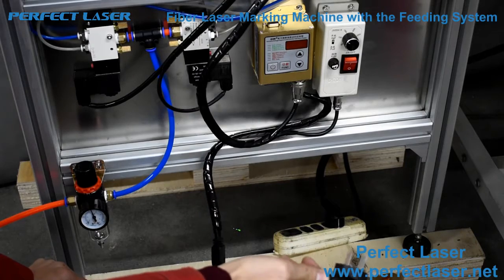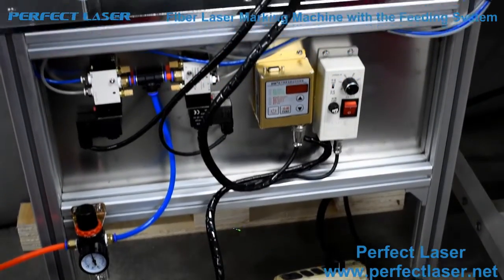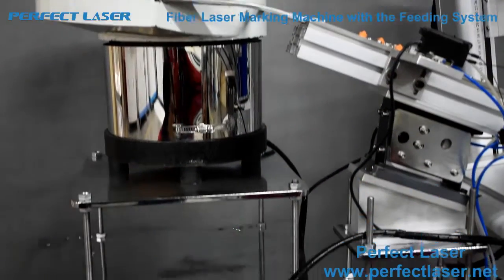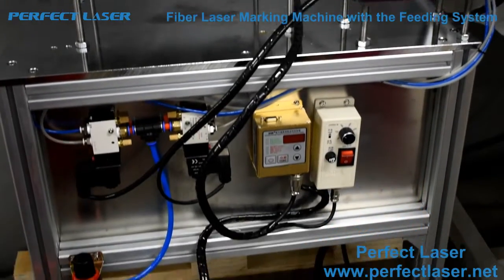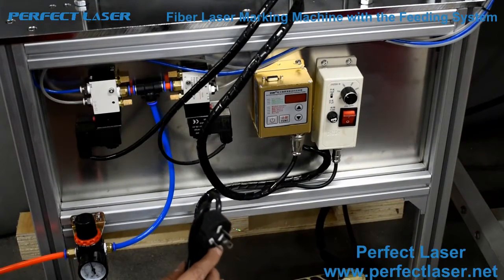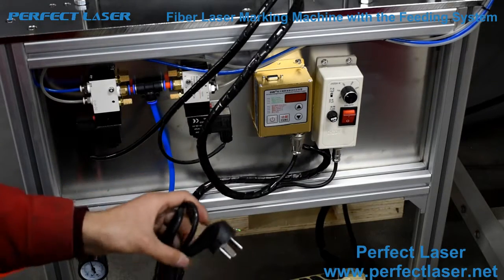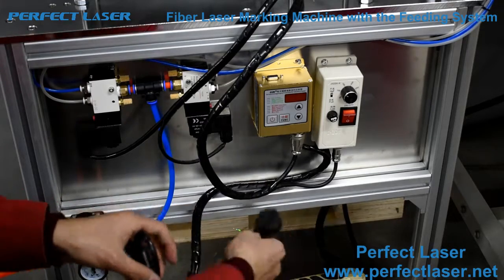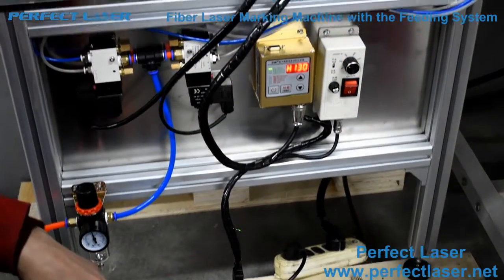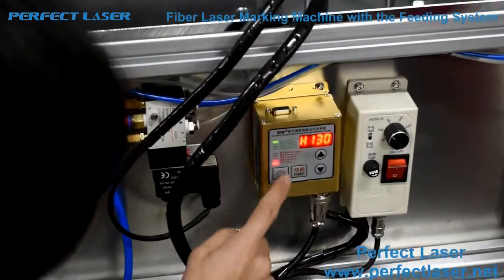Now the installation of the vibrating feeder. This feeder uses 220 volt single-phase AC. If your voltage is higher or lower, please use a transformer. Then connect the power. There is a power switch: press once to stop, press again to start.